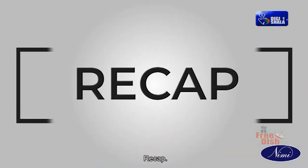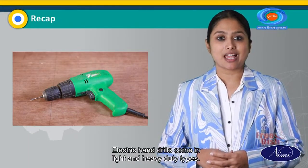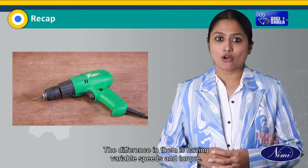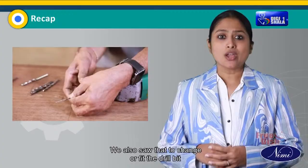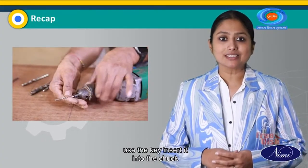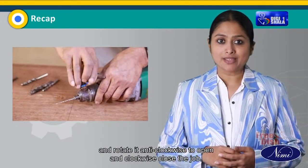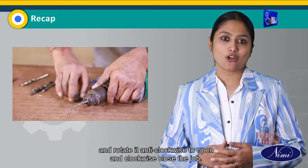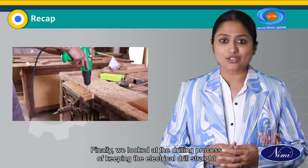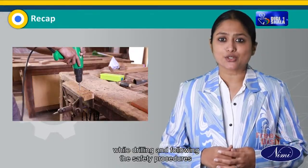Let's recap. Electric hand drills come in light and heavy duty types. The difference in them is having variable speeds and torque. We also saw that to change or fit the drill bit, use the key. Insert it into the chuck and rotate it anti-clockwise to open and clockwise to close the jaws. Finally, we looked at the drilling process of keeping the electrical drill straight while drilling and following the safety procedures that come with it.